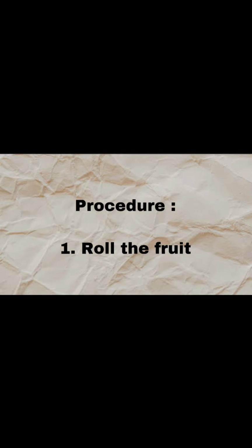So the materials that we use are fruit and vegetables. In my experiment, I use apple, orange, potato, and cucumber. We also use a zinc galvanized nail that is 2 inches long, and a copper strip. I use a coin as the copper strip, connecting wire, a knife to cut the fruit and vegetable, a multimeter to measure voltage and current, alligator clips, and an LED light that is 3 volt.